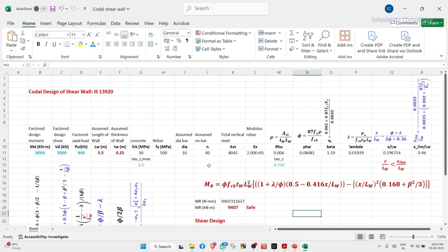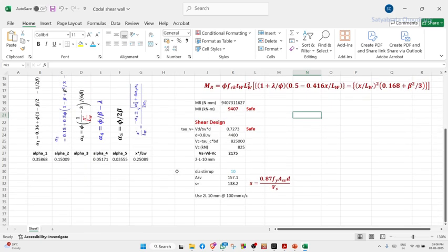There will be 2 layers of steel. In each layer you will put 20 bars. And see the spacing by calculating that it is 5.5 meter minus the clearance at the ends divided by the number of bars per mesh, which is 20. What is the spacing? If the spacing is very large, then you increase the number of bars. You cannot go below the 16 mm diameter. It will not be wise to use less than 16 mm diameter in a shear wall. So you can adjust the number of bars so that the spacing between the vertically running bars is not very large. After all, it is RCC, so the mesh is to be complete, the mesh is to be actually available.